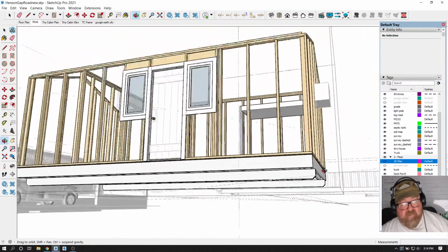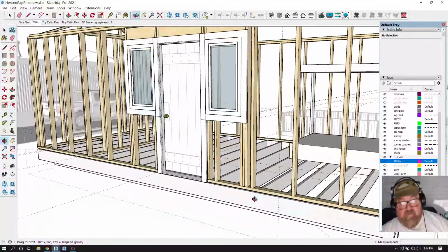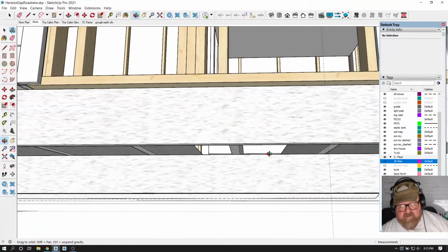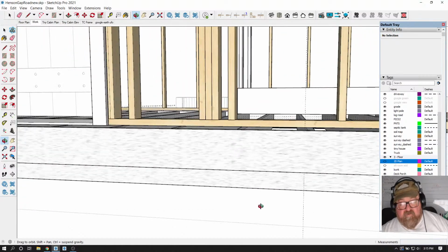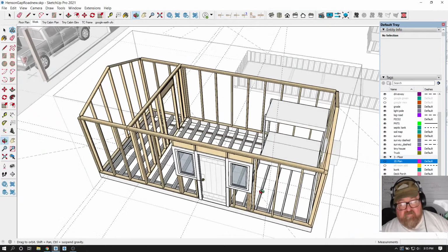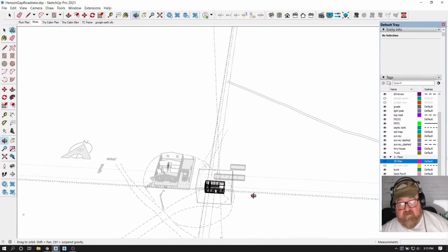Or I may just pick 3 or 4 points, like one on each end, and then every 6 feet do a heavy metal strap anchor. Probably at 6 feet I'll have a notch in this for a spreader bar, because most likely I would have my buddy with the boom truck come and pick this thing up and set it on a trailer and then haul it out here by the creek.